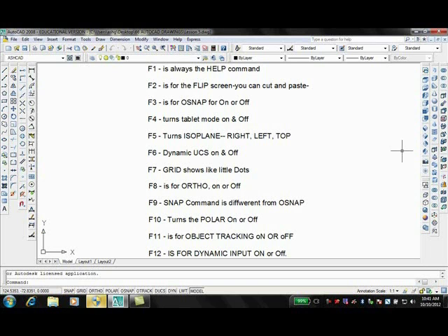In addition, when we start a line or circle or arc, and you hit escape, it stops a command. Furthermore, if we hit the enter key or spacebar, it repeats what was the last command. And if you hit escape, it stops the command, then you can hit spacebar to restart. For example, the line command. Finally, before I start to draw, I want to remind you to practice the undo and redo commands. They are very important as well.